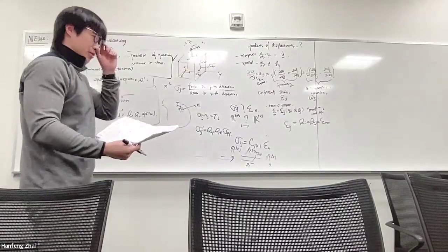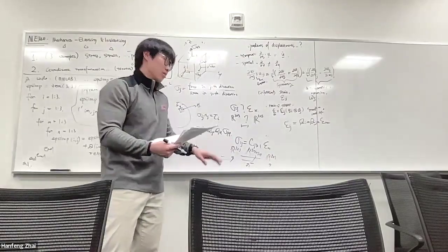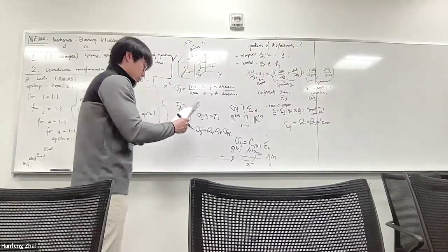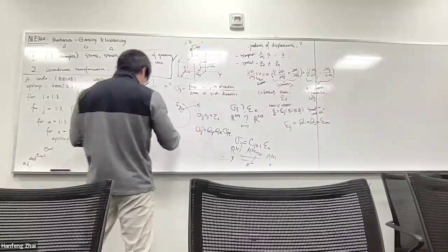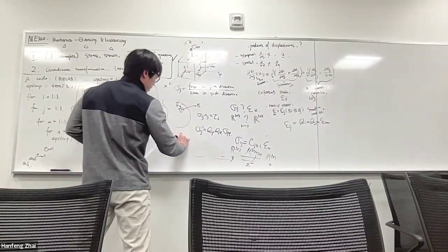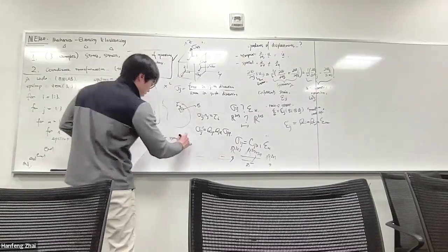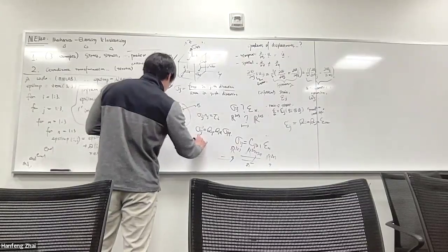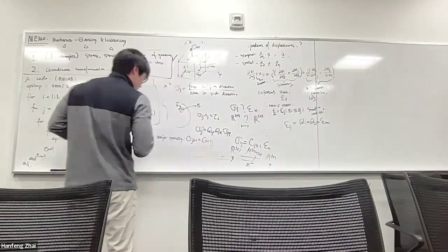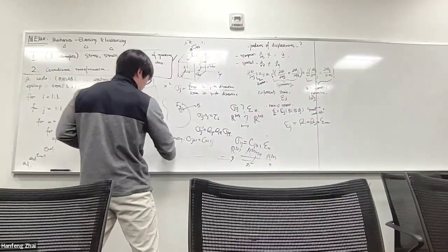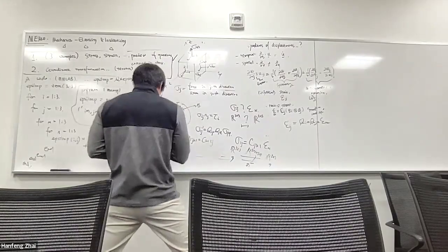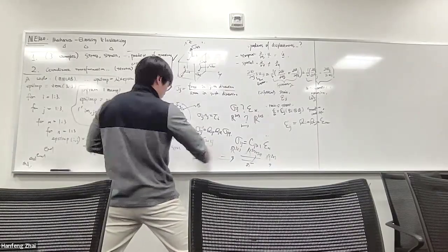But for this class, you will learn that we don't need to do a calculation that complicated. It can be reduced to a much lower degree of freedom using symmetry. There is one major symmetry, which will not be covered in detail today but you will learn later in this class, which is Cijkl equals Cklij. And 2 minor symmetries. Anyway, I'm just going to put it together.